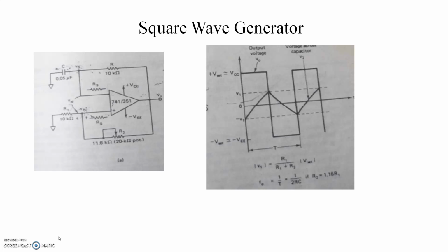But when the voltage V2 across the capacitor C is slightly more positive than V1, the input V1 minus V2 becomes a negative quantity, and hence the op-amp is forced to switch to negative saturation, minus Vsat. That is, when the capacitor is charged to a positive voltage, the differential voltage VID becomes negative, and since the input is negative, the output is forced to minus Vsat.